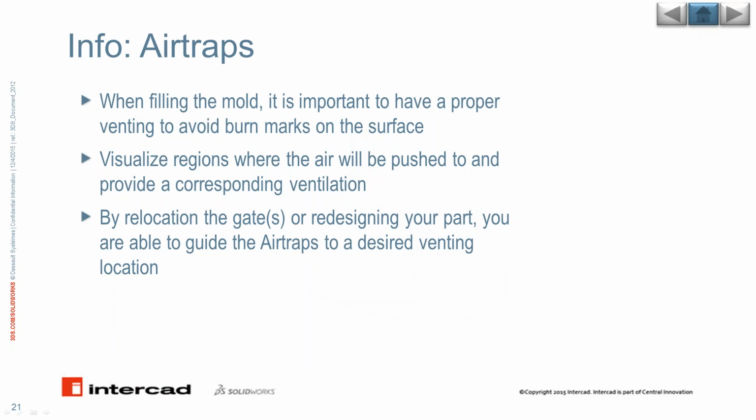So we can definitely have a look at when the air trap is happening and if there is any venting to avoid burn marks on the surfaces. And also we can have visualized regions where the air will be pushed and provide a corresponding ventilation. Okay.